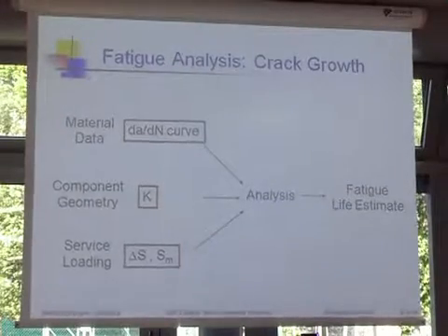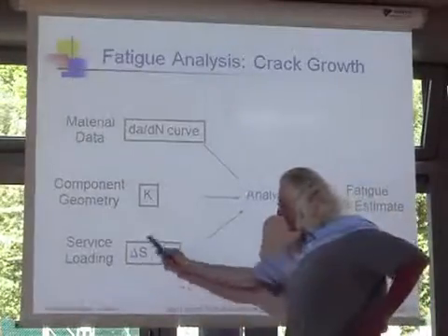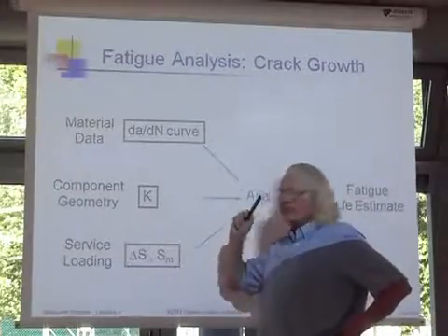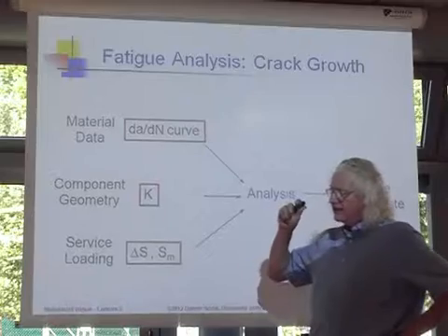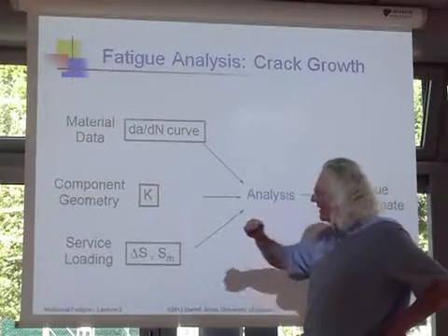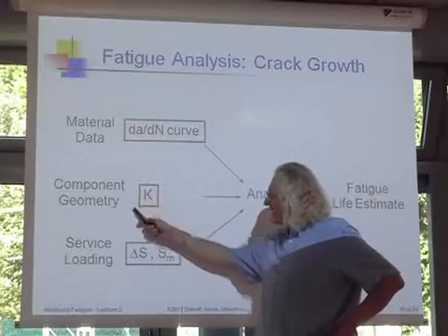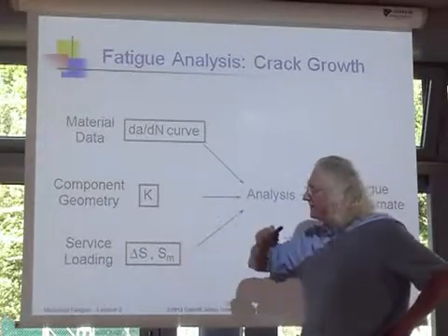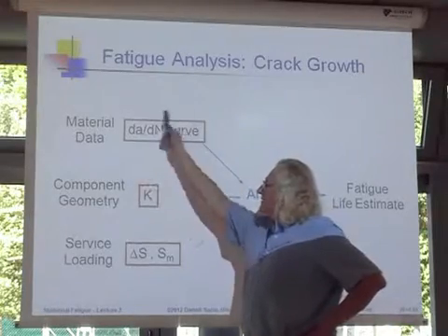My analysis template is pretty much the same. I need to know some things about the surface loading to make this work. Only now I'm going to do slightly different calculations. Rather than calculate stress concentration factors or deal with the stresses at different nodes, I now need to know the stress intensity factor, but it's calculated from the same theory of elasticity, so that one's easy enough. And now I need slightly different material data.